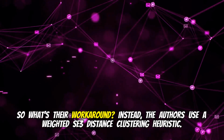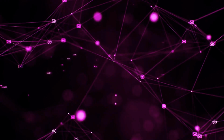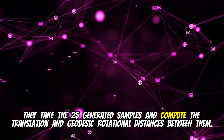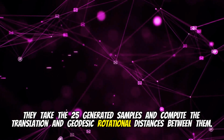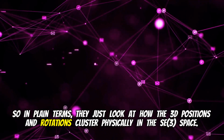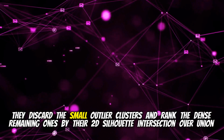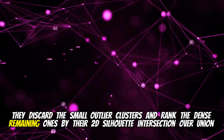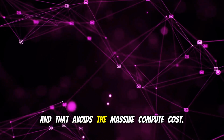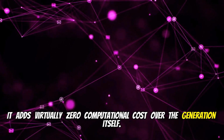So what's their workaround? Instead, the authors use a weighted SE3 distance clustering heuristic. SE3 clustering. Okay, break that down. They take the 25 generated samples and compute the translation and geodesic rotational distances between them. So in plain terms, they just look at how the 3D positions and rotations cluster physically in the SE3 space. Exactly. They discard the small outlier clusters and rank the dense remaining ones by their 2D silhouette intersection over union against the input mask. And that avoids the massive compute costs. It adds virtually zero computational cost over the generation itself.